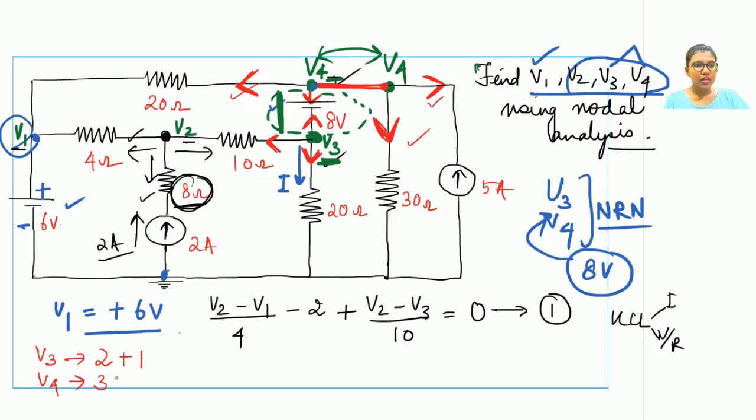So it can be written as 3 plus 1: 3 branches for which the KCL can be written, 1 which is common to the supernode branch. So together, the KCL for the supernode branch will have how many terms? It will have 2 plus 3, 5 terms in that KCL equation. So let us write down those 5 terms for the KCL equation.